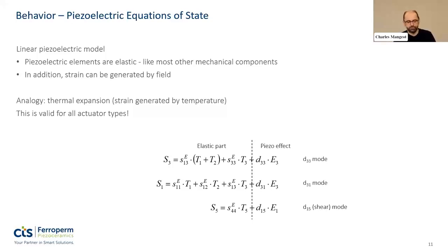If it's low levels of humidity, then it's generally okay. If it's contaminant, then it can be problematic. If it's clean oil, that's actually very good because it helps with the thermal conduction, but it doesn't affect the electrochemical degradation. So it's really case by case. If it's a contaminated environment, or very high humidity, for example, then I would recommend encapsulation, which is also something I'm going to mention in the actuator designs a little bit further down. Thank you. Sure.